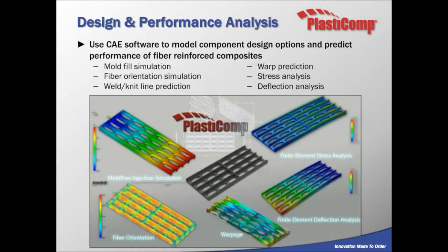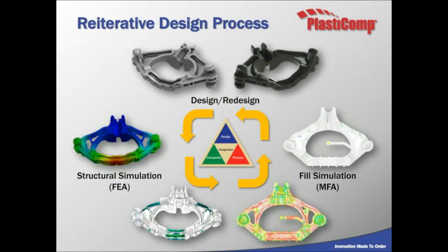Once again, there are a lot of simulations that we do to compare and take a look at, one being injection simulation, fiber orientation simulations, warpage simulations, and finite element analysis for the stress side and for the deflection side. As we look at all of these together, we can start looking at what is optimal for the geometry. How clients typically deal with us to learn more about what is optimal or moldable for their geometry is that they send us the geometry that they have. And then we have discussions, maybe we'll attend in person or have a video conference.